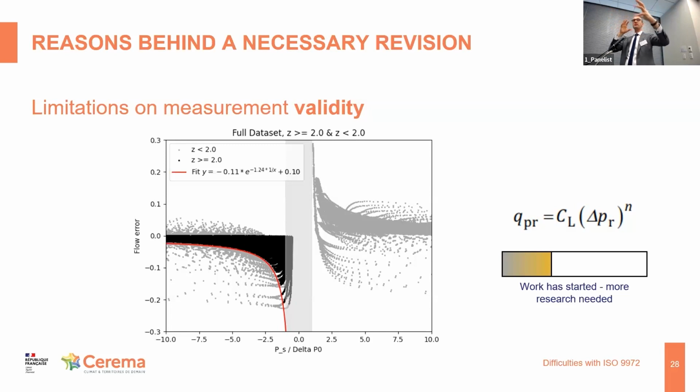So we excluded these points to make it more reasonable. Then all the gray points disappear and we only have the black points. And this is very interesting. With these black points, this is the result for a pressurization test. We can define a curve of maximal possible error, and this is the fit of these maximum curve points. It's given here and over there. If you have a measured zero flow pressure and a pressure station at, say, 50 Pascal, you can give the respective error for this pressure station.